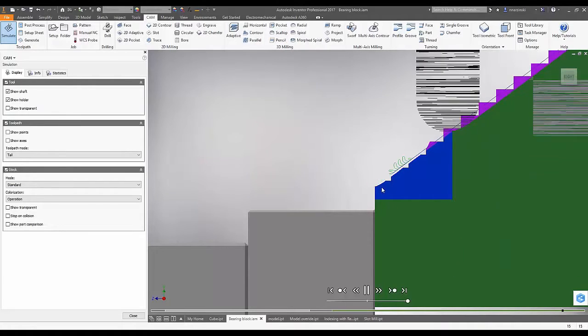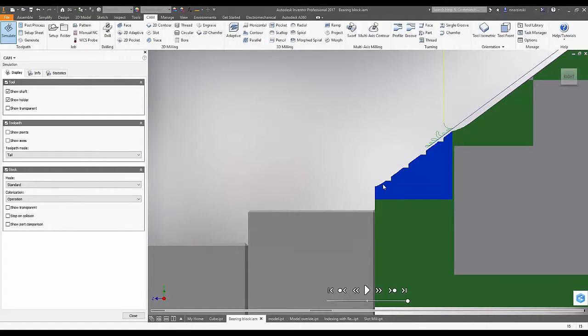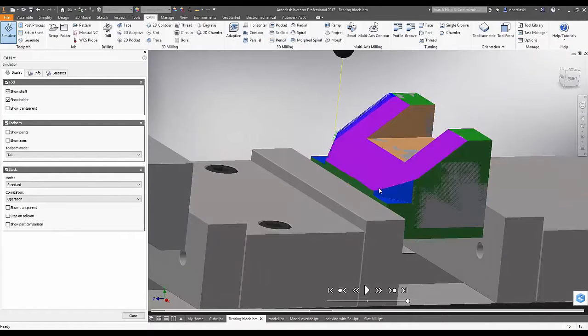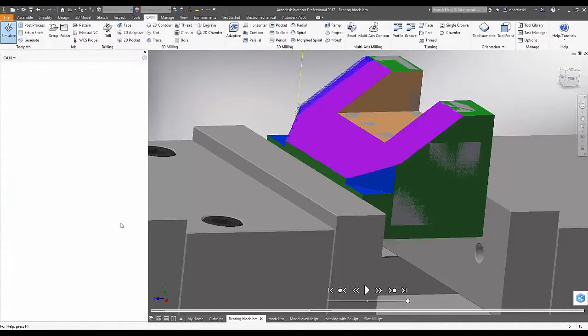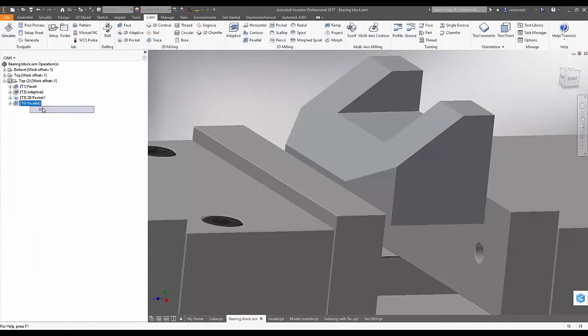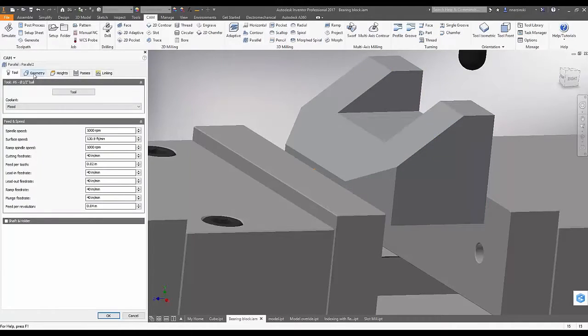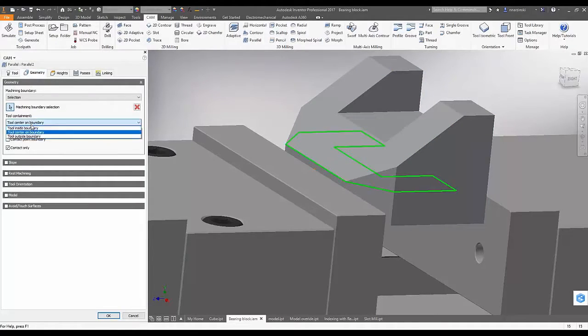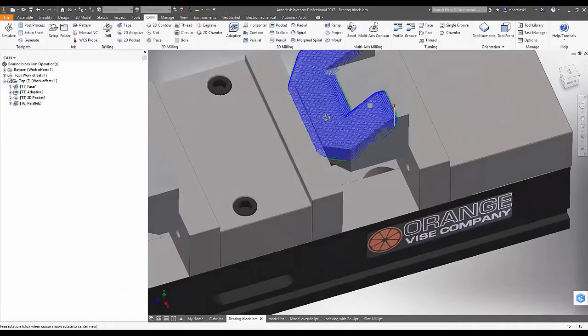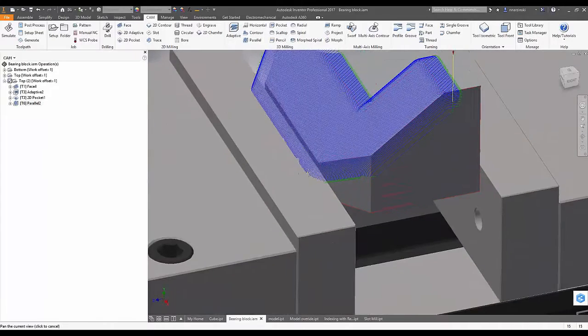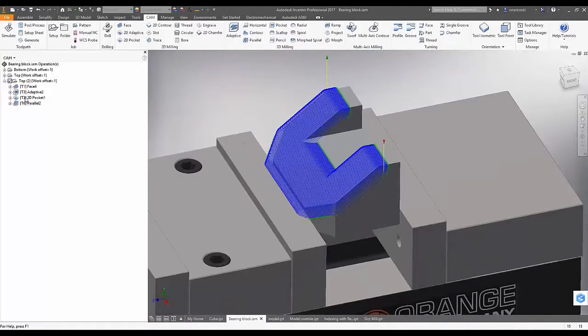the tip of the tool is going to leave a little radius down here at the front edge of the part. So we want to come in and remove that, as well as these little cusps over here, because the tool can't go outside the edge of that part that we selected. So what I'm going to do is go back in there and change that to tool outside boundary. And say okay, and then you're going to run into what we saw earlier, where the tool actually wraps around the face of the part.